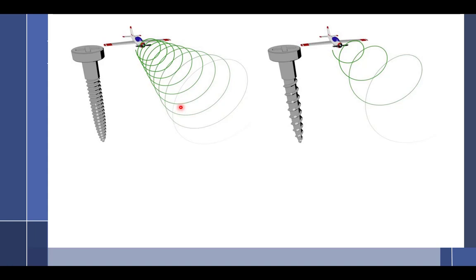For climbing, it's more efficient. Don't make me say plank again. One of the problems with this one over here is if I have both of these aircraft on the ground and I do a static run-up, which one's going to have the higher RPM? The fine one, which means more horsepower.